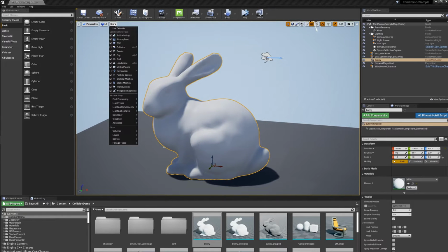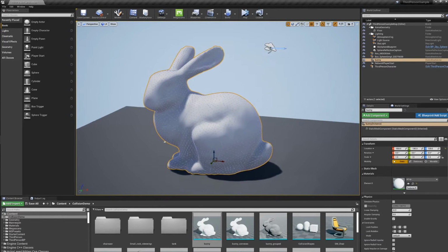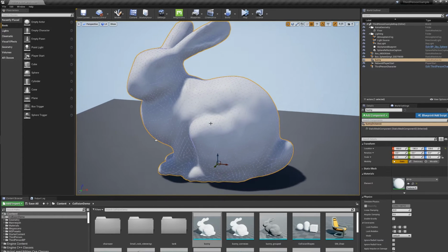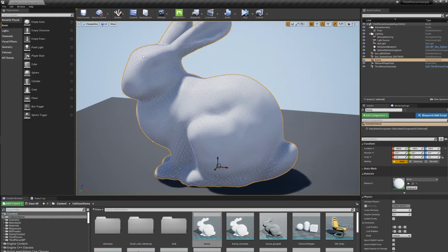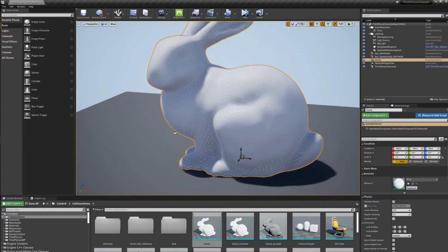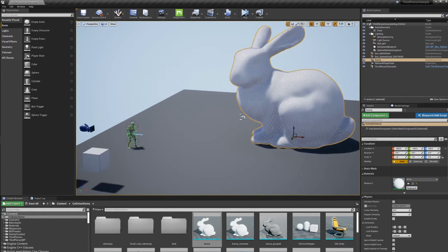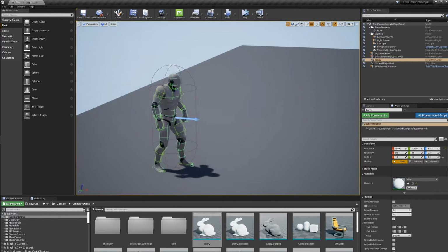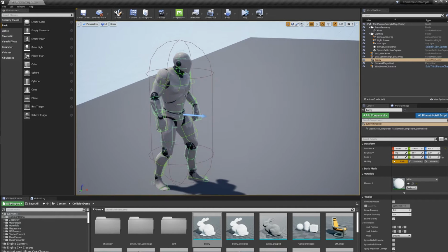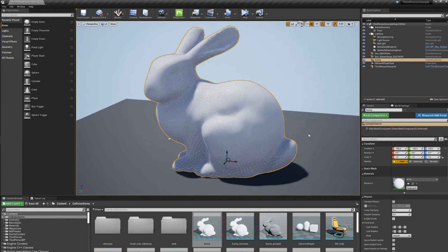There's a show flag here. If you go to Show and turn on Collision, that's the Alt-C hotkey, but only when you're in the viewport, you can hopefully see that now there's this kind of overlay triangle mesh, and that's the collision geometry. You can see it's actually just the mesh triangles. And if we compare that over here to this standard character, you see it has these simpler shapes. If I toggle it on and off, you'll see them, these kind of like tubes and boxes. For this character, that's the collision representation. I'll talk more about that in a little bit.